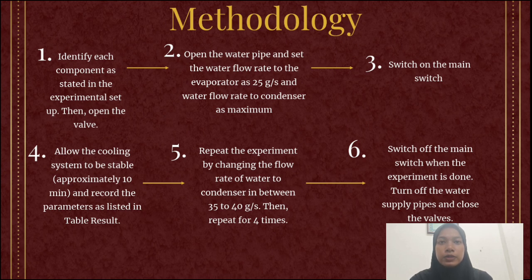We switch off the main switch and turn off the water supply pipes after 1 minute, then followed by closing the valve to the shutdown position. The reason to keep water running for a minute is due to the residual heat removal. Because keeping the water running allows the system to cool down gradually, which prevents thermal stress and protects the components.